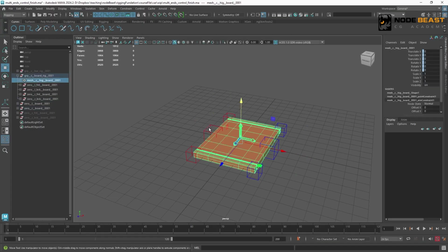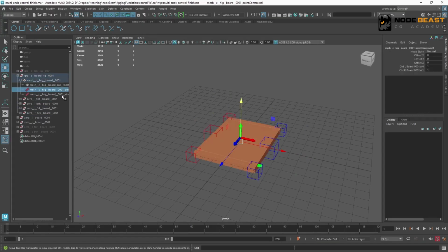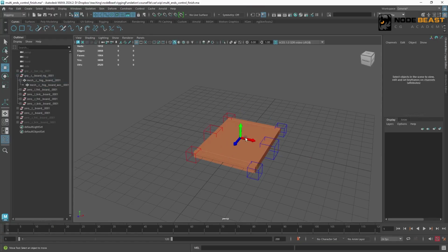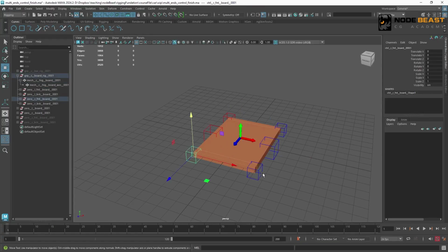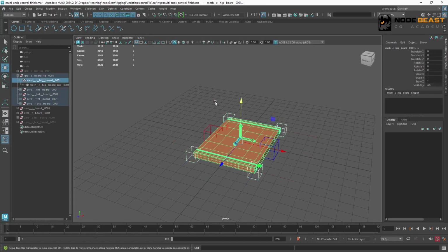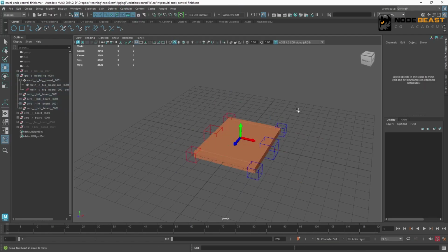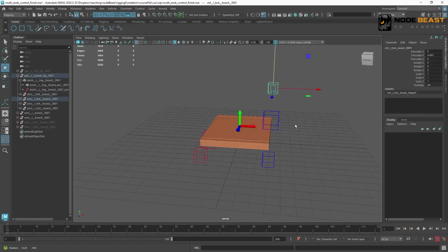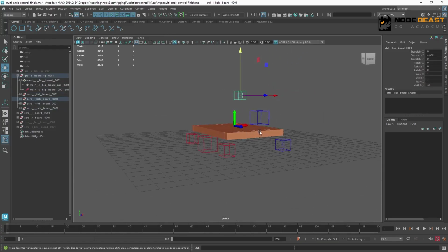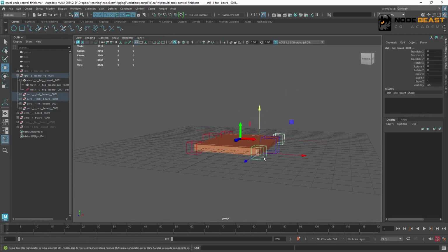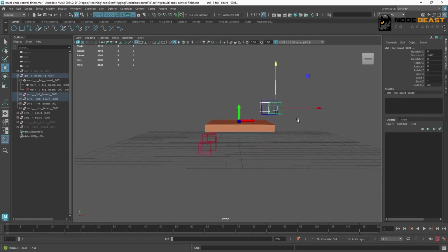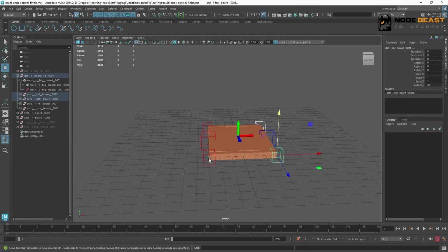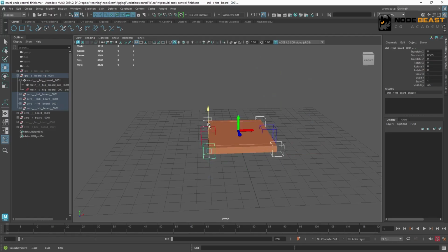To simplify the operation, we can delete the 2 constraints we had. For the position, it's obvious. It's just using the 4 controllers to apply a point constraint to it. This way, they each control 25% of it. So when we move 1, it has a 25% influence. And if 2 move together, it's a 50% influence. And if all 4 move together, it's 100% moving the model up.